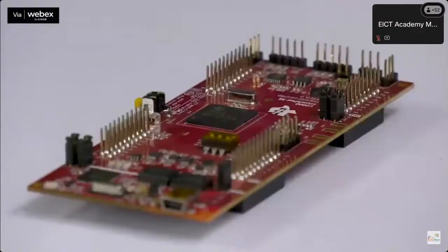Let's look into the most important part of this hardware demonstration, which is mainly the DSP controller. We have used a Texas Instruments TMS320F28379D DSP controller to control the inverter between the AC grid and the DC microgrid. The DSP controller is the most economical controller used for grid integration applications.